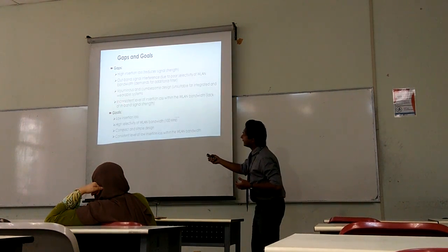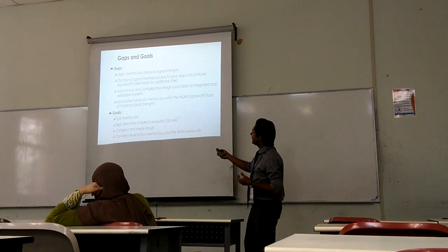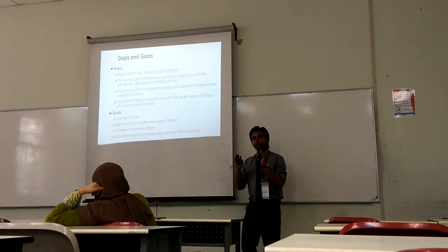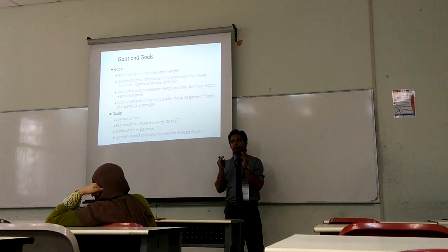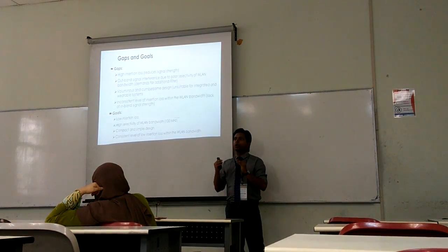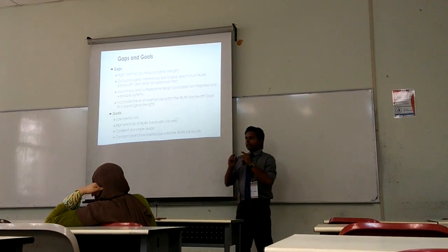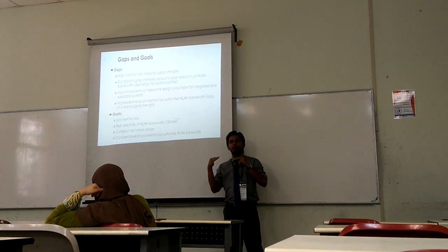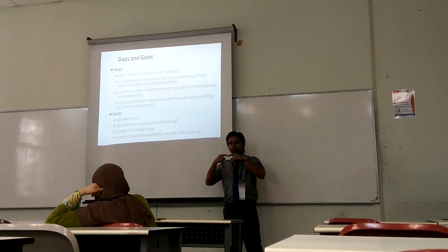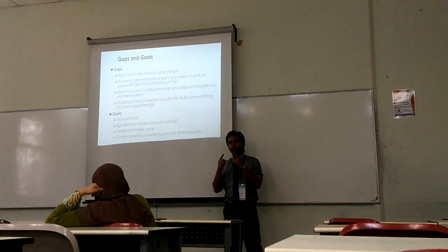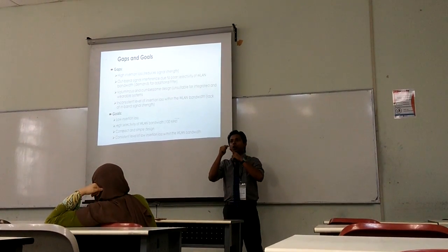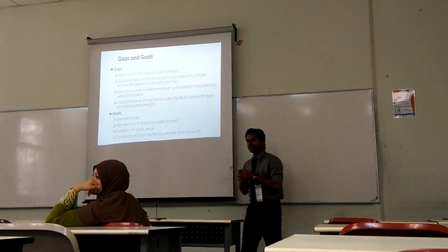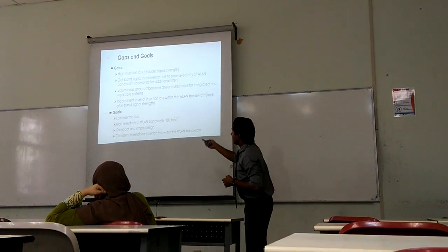And this is an interesting thing: inconsistent level of insertion loss within the WLAN bandwidth. If we consider the WLAN bandwidth of 100 megahertz and look at the level of insertion loss, most of the filters have no maximally flat gain. So there's inconsistency of insertion loss. Mostly there's a peak at the top, and then it suddenly and rapidly goes down. So this is another drawback of the recent trends.